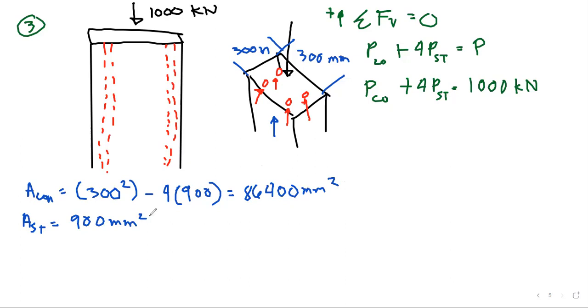The moduli of elasticity. For steel it is 200 GPa, and for concrete it is 14 GPa. Technically, the force is in kilonewton, the modulus in gigapascal, and the length in millimeter, so it is as is. Nothing to change.